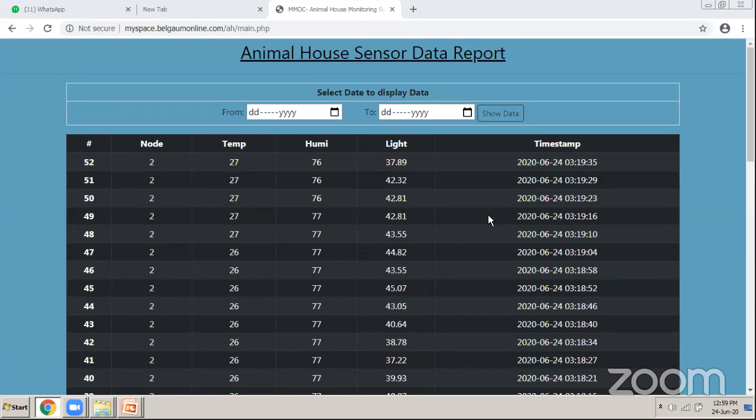Now, the problem is that to move it in the forward or backward direction, you have to control the rotation of the shaft, the rotation of the DC motors. And to control the rotation of the DC motors, you require a motor controlling or motor driving shield, which has to be put. I am definitely sure he is using that shield. Otherwise, you cannot directly drive a DC motor from Arduino GPIO pins. It's not possible. You have to use a shield. He must be using it. So he has to use that shield and write the appropriate code. It is a little lengthy to explain here, but extra hardware is required. That is the motor driving shield. Please remember that.